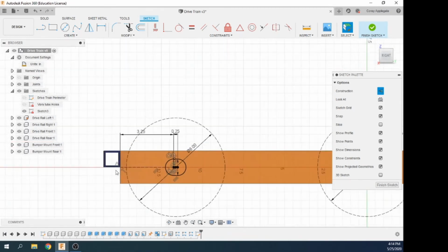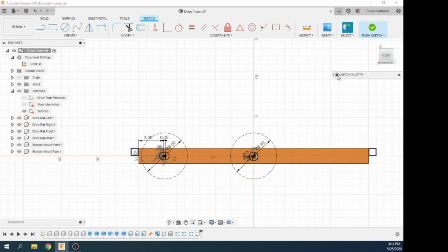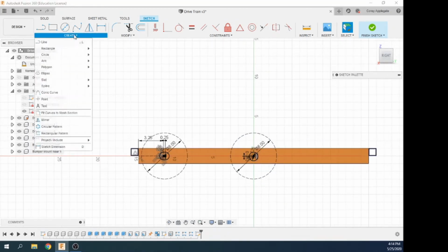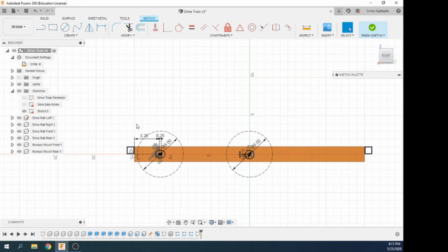We could go ahead and redraw all this over on the other side, but we're going to use a mirror. Since most of our chassis are always going to be equal distance from center wheel out in both directions, the mirror command works well. First thing we do is select our objects, we want to window select what we want to mirror.